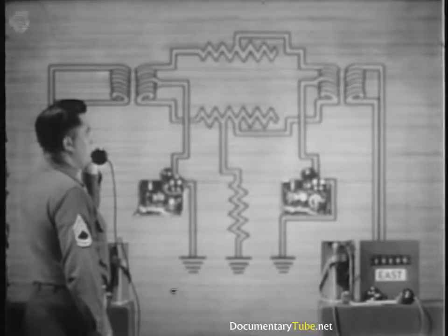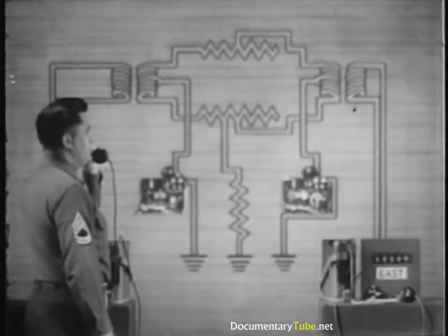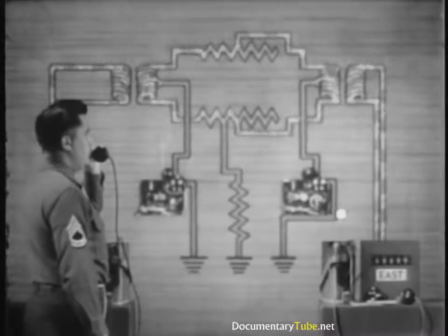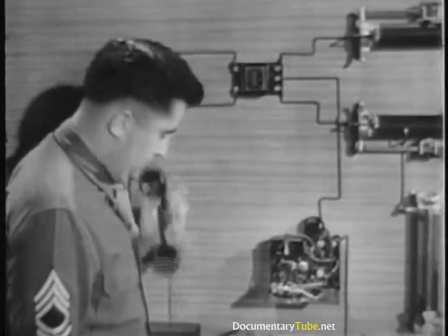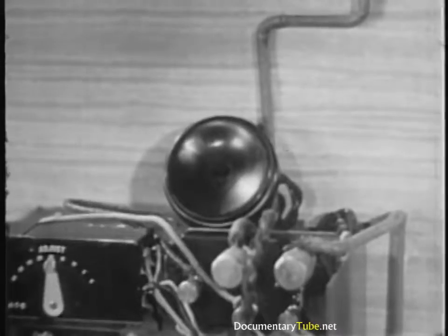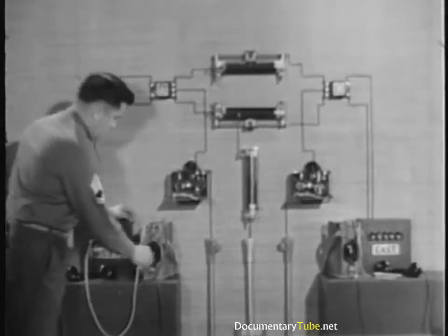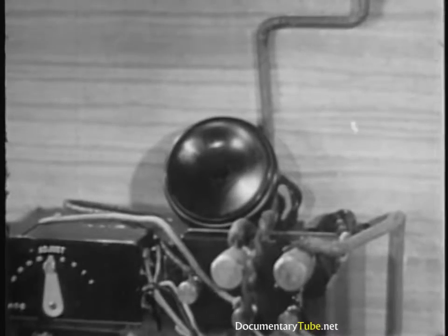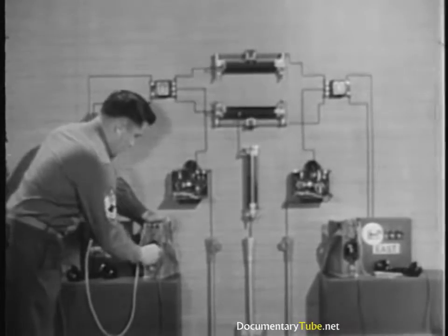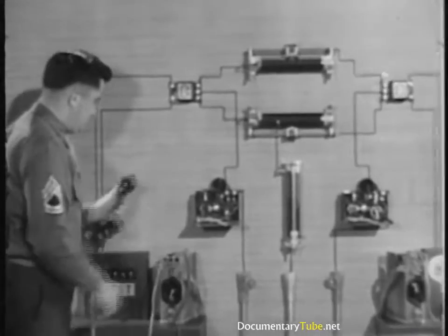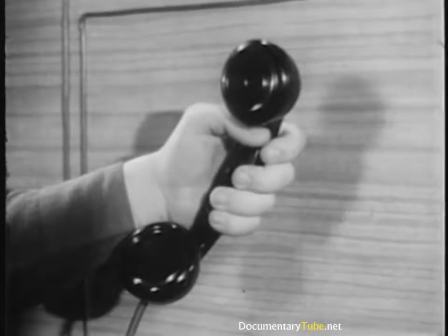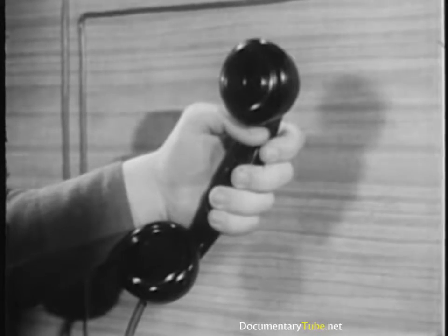We have seen before that this higher frequency current cannot travel through a telegraph instrument. Consequently, it follows its normal path. Ordinarily, the telegraph channel is still usable unless the diverted ringing current is strong enough to cause interference. The telephone channel is still okay too, but its quality may be somewhat impaired by key thumps. And like any other grounded circuit, it's apt to be noisy.